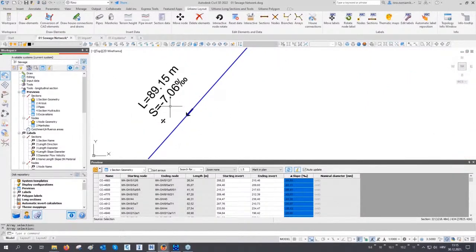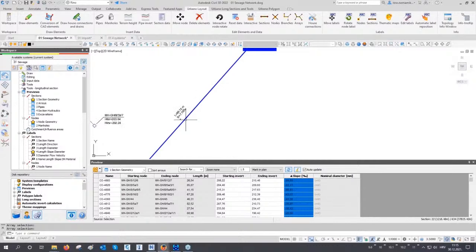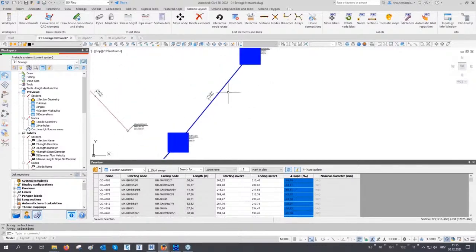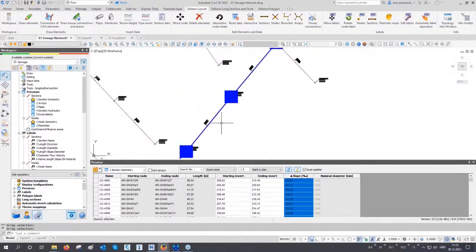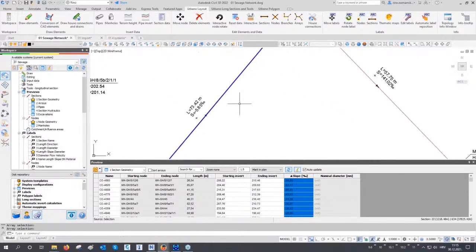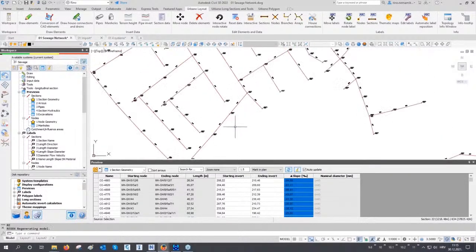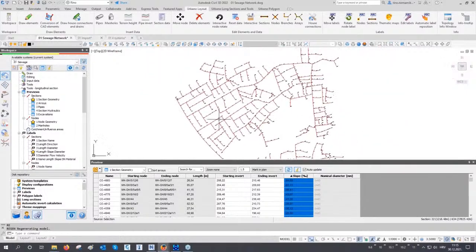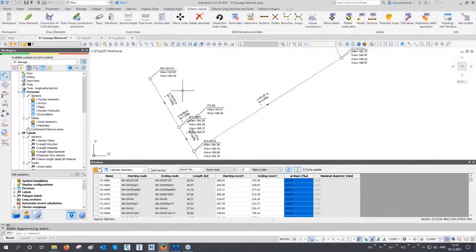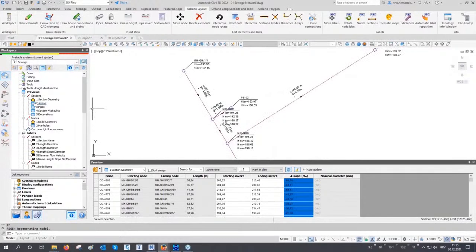We can see that the slopes are negative, and we have these arrows which represent drawing order. They are opposite of the flow direction. So obviously there were some mistakes in the original shapefiles. Basically, starting and ending nodes were reversed. So how can we resolve that? Of course, we can reverse one branch by branch, or we can run one really nice function.